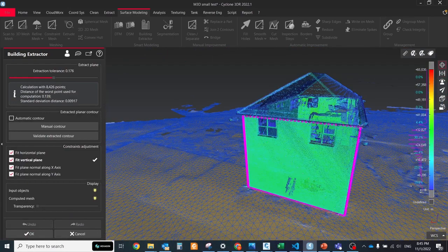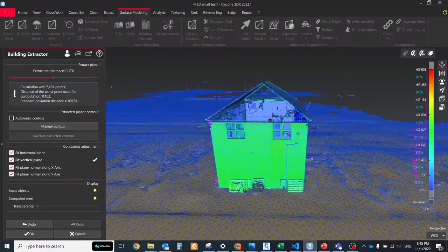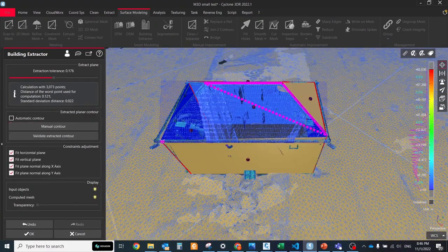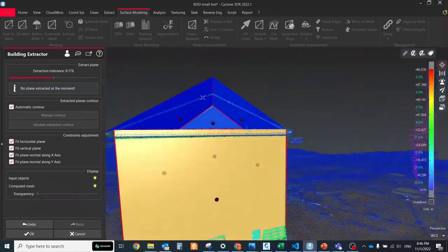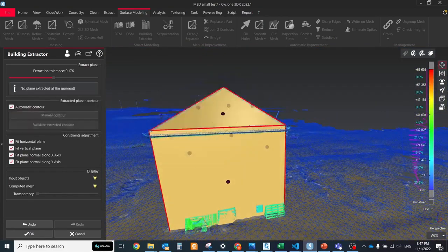The user can manually define a plane by clicking on any number of points with the Shift key pressed. Pressing the Shift key will override the automatic plane extraction behavior. All points clicked with the Shift key pressed will be used to compute the best plane from these endpoints.